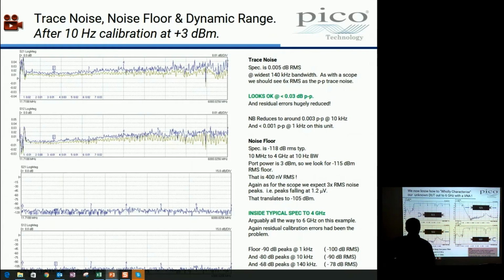Did anything move? Yeah, so I think you conclude it's a well-behaved steep and deep low-pass filter. To a degree, it's re-entrant around 4.2 gigs. Match is not brilliant, but it's okay, out to a gigahertz. As a general guide, match minus 20 dB is pretty good for most microwave applications.